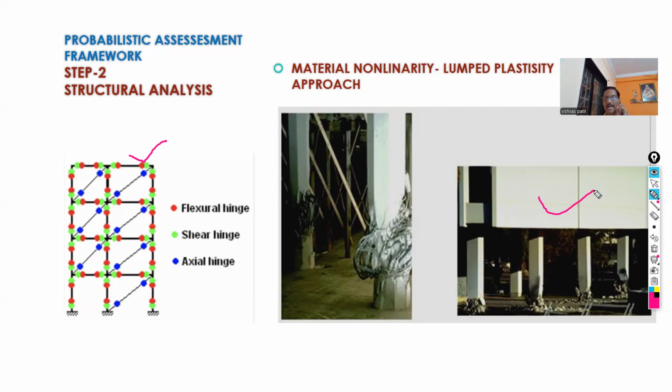Second, when the frame is subjected to lateral load, the bending moment is maximum at the ends of the member. So flexural stresses are concentrated at the ends, and therefore the element is likely to fail at the ends only. Therefore, in the lumped plasticity approach, the nonlinearity is assigned at the ends.